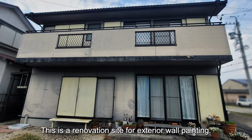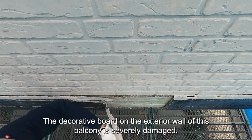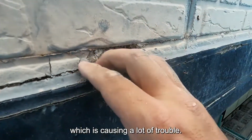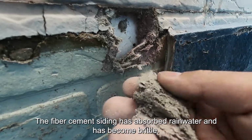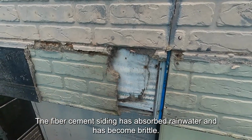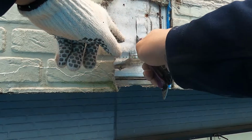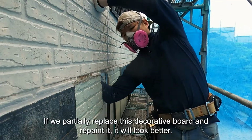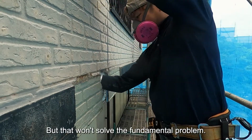This is a renovation site for exterior wall painting. The decorative board on the exterior wall of this balcony is severely damaged, which is causing a lot of trouble. The fiber cement siding has absorbed rainwater and has become brittle. If we partially replace this decorative board and repaint it, it will look better. But that won't solve the fundamental problem.